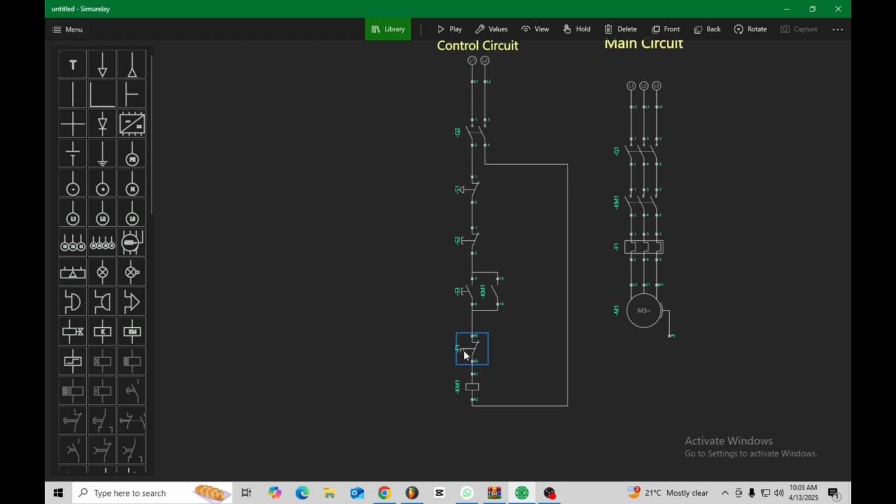Okay, cool. And this you can pretty much add anywhere in line of this circuit, but this is the overload relay, right? This is the normally closed contact on the overload relay. So when the overload relay notices a trip condition, this circuit will open and there'll be no power being supplied into your control circuit, thus your main contactor will not close. And when you reset the overload, then this comes back on. And then if it trips again, you just know that the fault is somewhere below the overload relay.